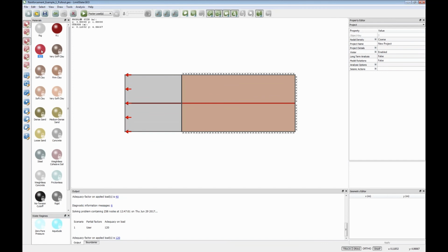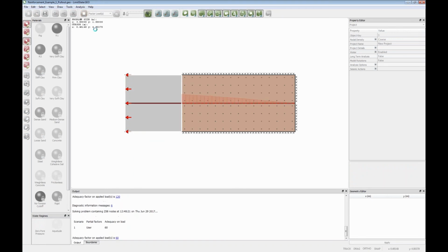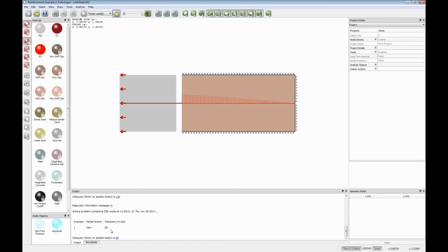Finally, what I'll do is illustrate one other feature here. We have the rupture strength here, so that's basically the tensile strength of the reinforcement. Currently we've set it to effectively infinity, 1E30. If I set that to 60, then it will fail in tension at a stress of 60, and if I solve that, you can see that now the collapse load has gone down to 60. It's modeling the axial stresses building up fairly linearly here, but they finish at 60 at this point.